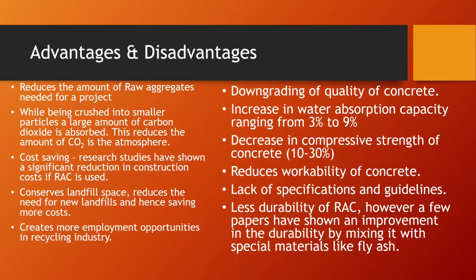Like asbestos, I think you all know asbestos is very, very dangerous, only if you're working with it, if you're cutting it or you're moving it, when the particles start moving around in the air. Asbestos, when it's just sat there in a form, like a panel or a roof tile, it's not dangerous at all, because it's captured, it's inert. It's no longer a live element until, as I say, you start breaking up the material itself, and then it becomes the airborne particles, and that's when it starts to become a real issue.